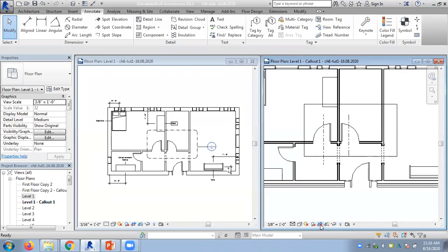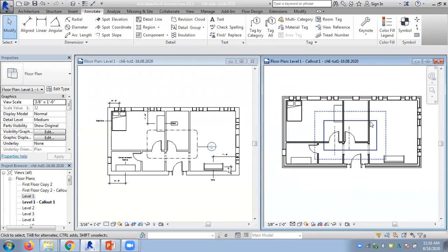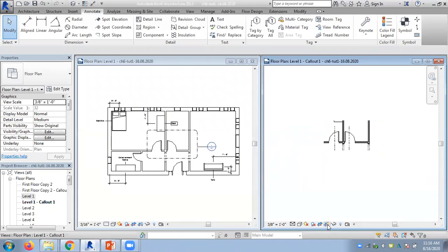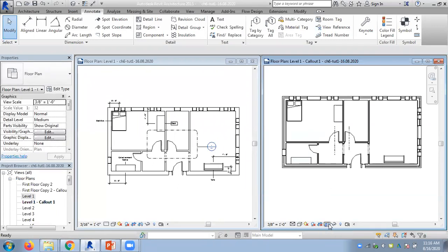So you get the big picture. So I have this call out to here, but I can say don't hide it. So unhide the others, and you can hide the boundary also. So this way, these two buttons will help you to hide and unhide the crop view as well as the boundary. So it's almost the same picture,